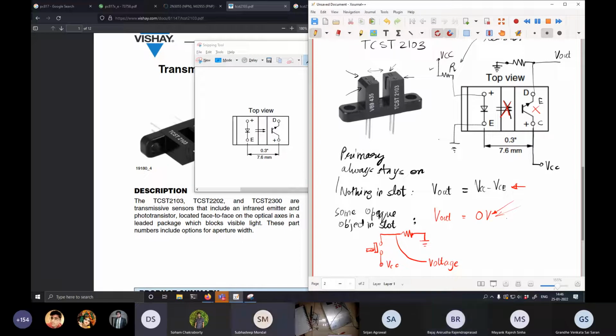Yes, I got it. And when this switch is switched on, I can do very cheap animations over here. So when this switch is on, then this becomes VCC, and so this becomes VCC. And obviously there's a collector emitter drop over here, and so that drop gets subtracted from VCC. All right. Yes, sir. Okay, good. So let me open the switch again.